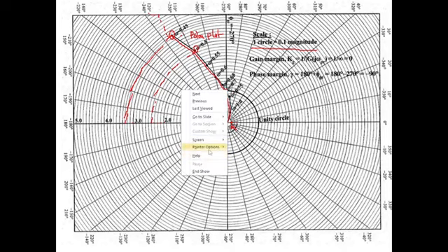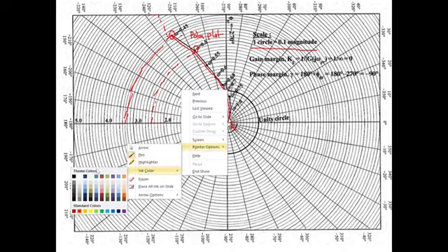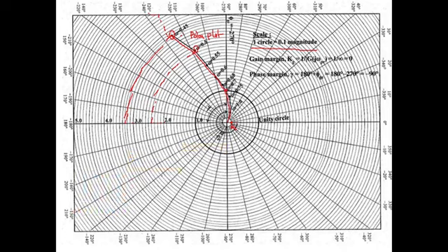From this, you have to draw a line, right? So you will draw a line like this. So now we can see that the corresponding phase at the gain crossover frequency is 270. So the corresponding phase, phi gc, is here equal to 270 degrees. But if you want to find the phase margin gamma, you have to use 180 degrees plus phi gc. So here phi gc is 270, so 180 plus 270. So the answer is minus 90 degrees.